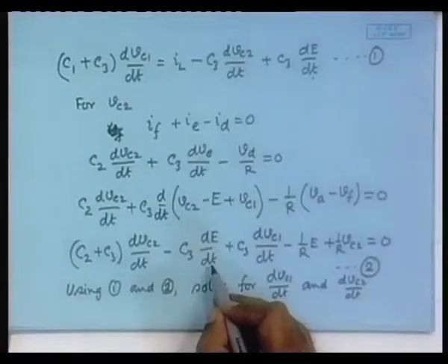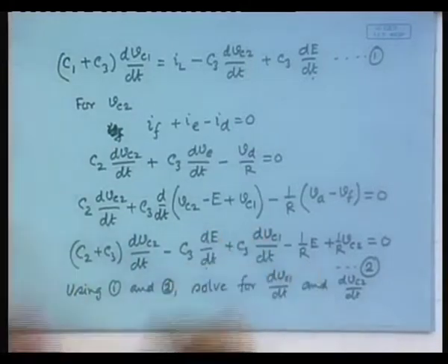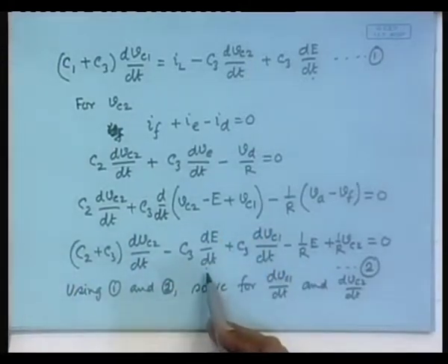Could be sinusoid, in which case you are happy, if you differentiate it you get a cosinusoid, fine. But what if it is a square wave? You can easily apply a square wave because all that you need to do is to connect that kind of a circuit and turn on a signal generator with a square wave input. Then this particular thing will have to be solved, and when you write the program, obviously this will assume infinite values at the transition points. So, at the transition points this term will assume infinite values, your program will not be solvable, and in fact if you connect it like that, the circuit will have problems.